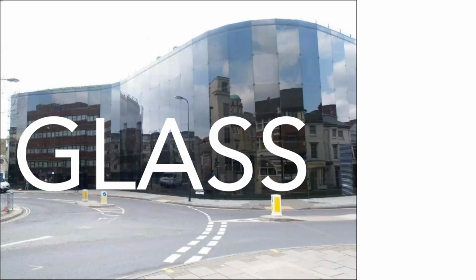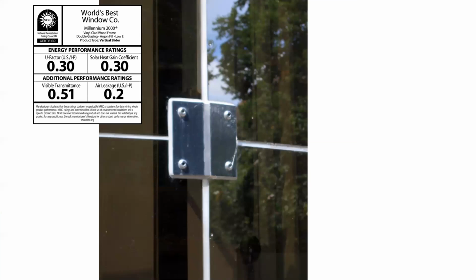Okay, so now I will quickly go over window properties. There are all types of glass, and window performance is largely based off what you see on this NFRC rating label. NFRC is the National Fenestration Rating Council. So we're going to be looking at U factor, solar heat gain coefficient, visible transmittance, and not really that much at air leakage. And I will go over these 4 concepts in the next few slides.